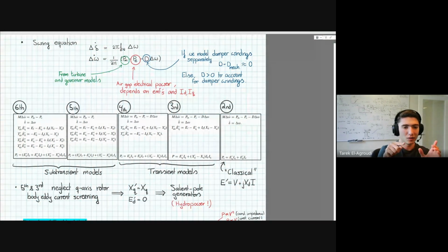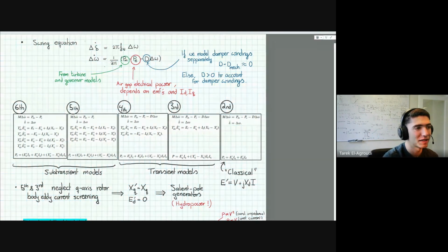And so when you have some DC current going in the rotor, generating some constant voltage, which rotates with the speed of the rotor, and the opposing electrical power on the stator windings also generates an opposing torque, you basically have 2 forces which rotate with an angle. And the angle between these forces is the power angle. And of course, when the rotor accelerates, this angle increases, and when it decelerates, it decreases. And the swinging of this angle from this sort of steady state, that's sort of what the swing equation describes.